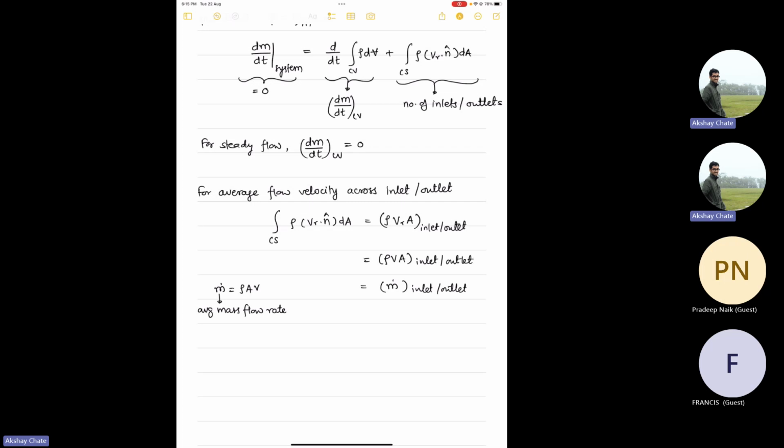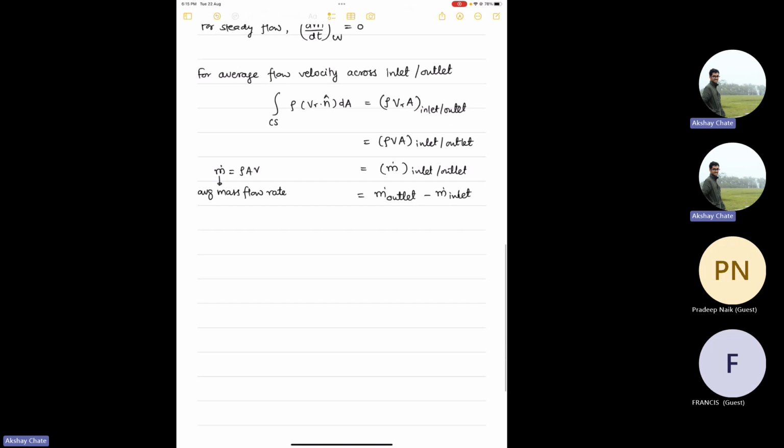And again there is a general sign convention that I discussed in the last class: when your area normal aligns with your velocity, then your dot product becomes positive, and when the angle between them is 180 degrees, it's negative. So therefore, we consider outlet as positive because the outlet velocity and the surface normal are in the same direction, and generally the mass entering your system is considered negative. This is the sign convention, so nothing major about it. Just to get familiarized, we'll solve an example.